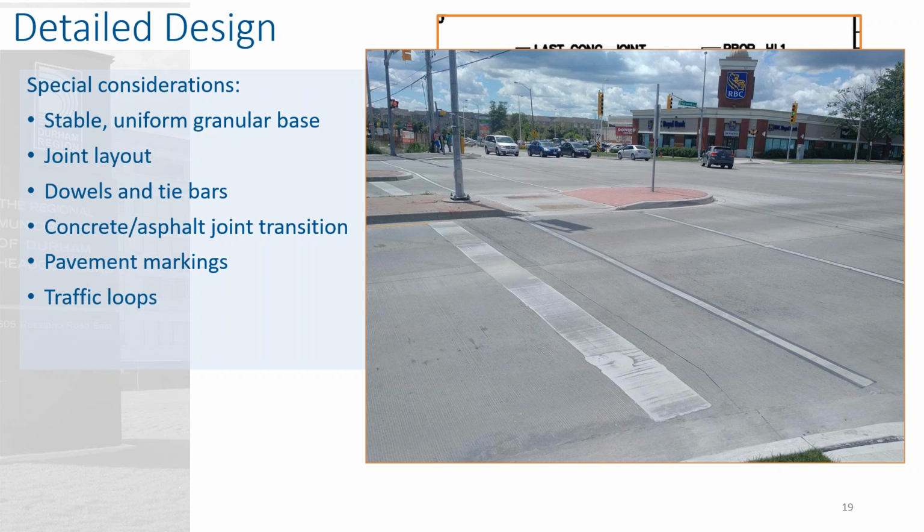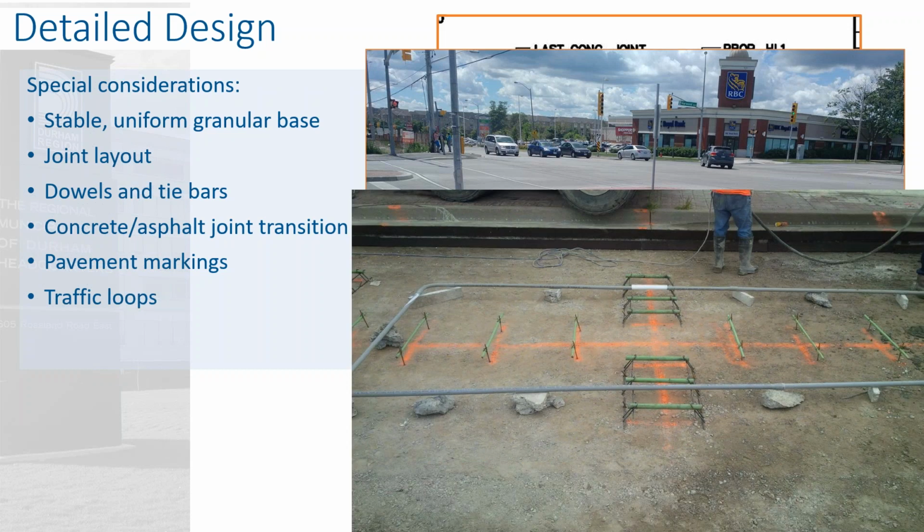And then traffic loops was another consideration. We didn't want that to be cut into the new concrete, so we ended up using preformed loops that was set right on the granular.